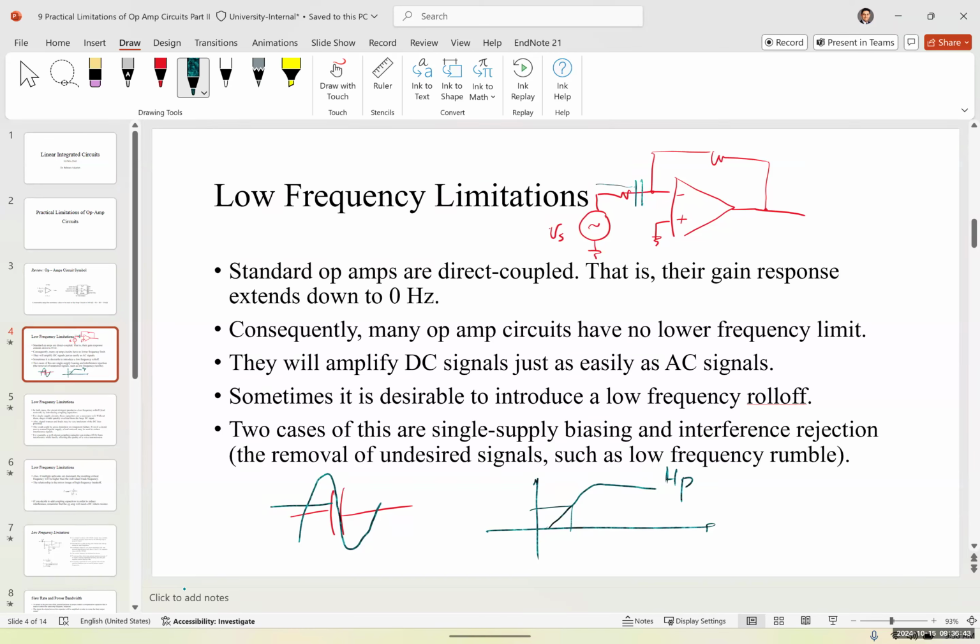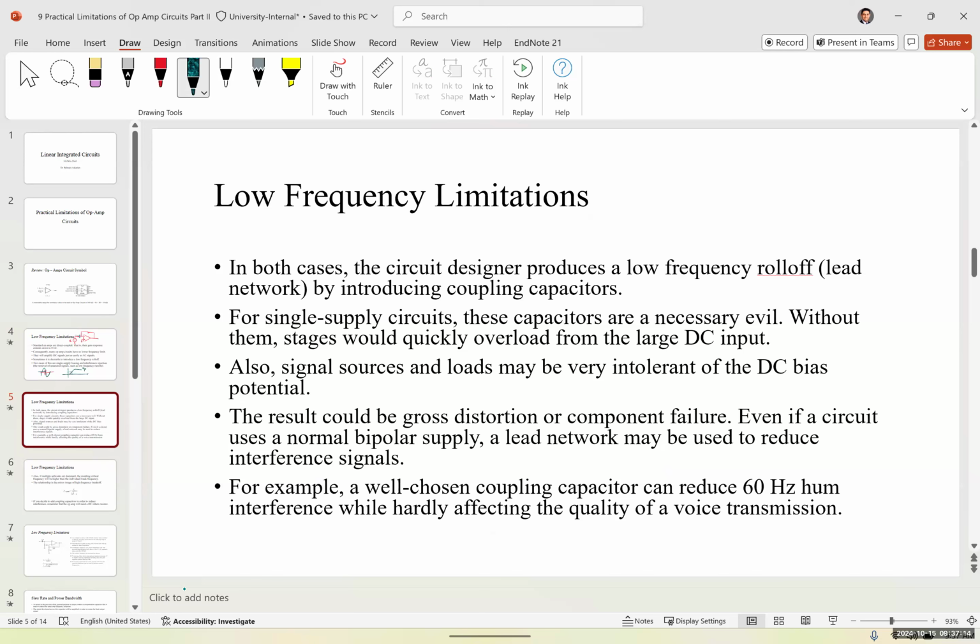They are very sensitive to lower frequencies, and these cause undesirable noise on the signal. So we want to filter that out. To filter that out, we can use a capacitor. Okay, now we have added a capacitor to get rid of noise or any undesired DC signal. Now that has changed our cutoff frequency. How can we determine that cutoff frequency when we have a coupling capacitor?